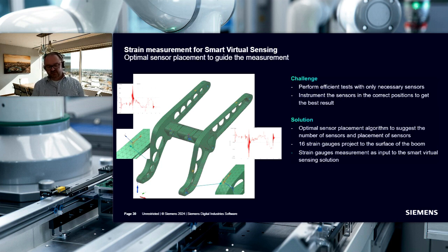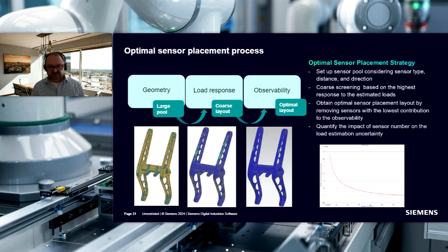First, you tell the system where you can place measurements, and then it tries to minimize the amount of measurements needed. They can be quite far away from the load application points, and can also have influence from different load application points at the same point. And the tool tells you the best, or optimal, places for the measurements.